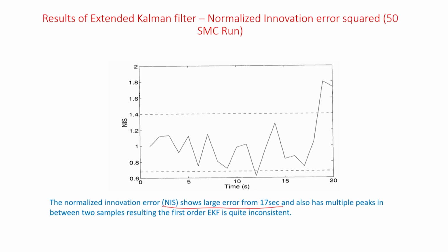So, the Kalman filter is nothing but an optimal observer, Luenberger optimal, because in the deterministic sense in control theory you know something called the Luenberger observer. In the Luenberger observer, the system has to be fully observable. So, you see A prime, A dash C, A dash square C, that matrix, the observability matrix, has to be full rank, from a deterministic point of view. Similarly, if you do Lie derivatives and stochastic system observability, you will say Kalman filter observability is also proven.